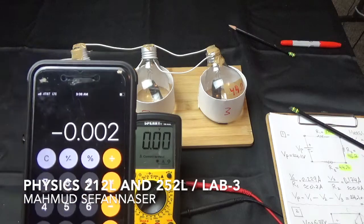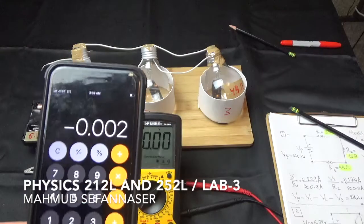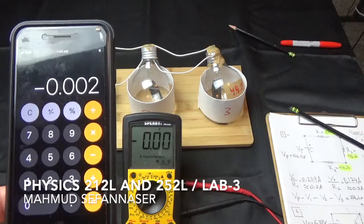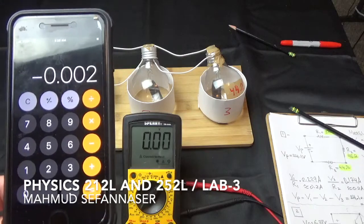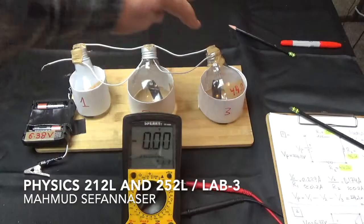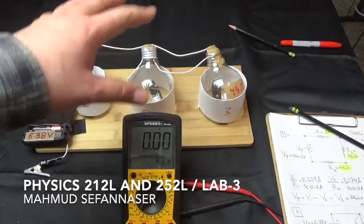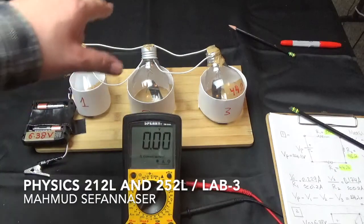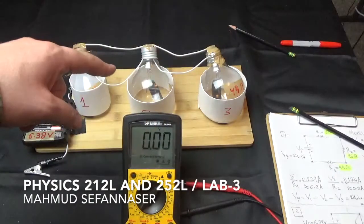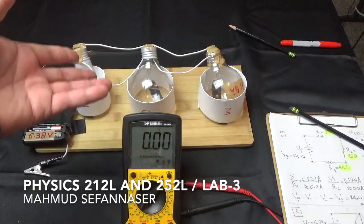And you learned something, guys. When you connect the resistors in parallel, you will have the same voltage across each one of the resistors. If you connect them in series, you will notice that the voltage is different, but the current that flows in this circuit is the same. So this is in series.